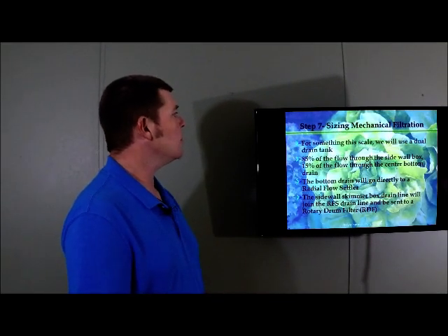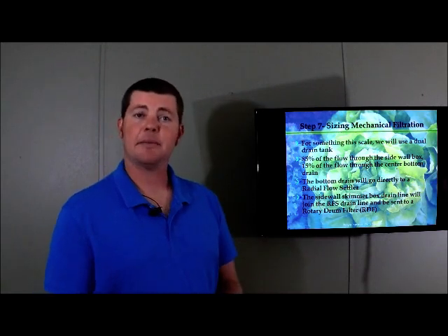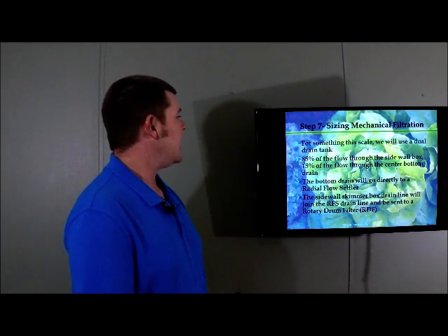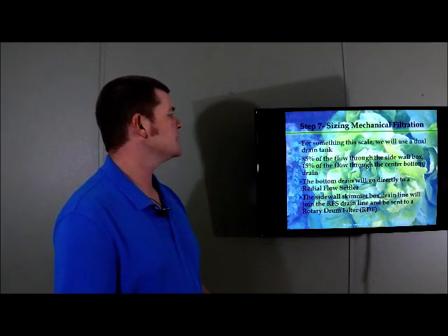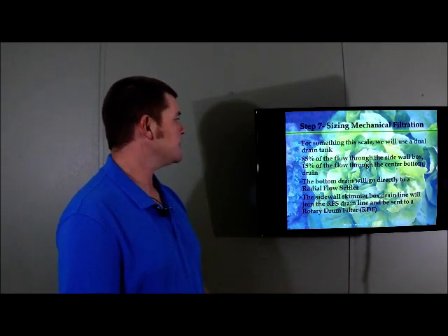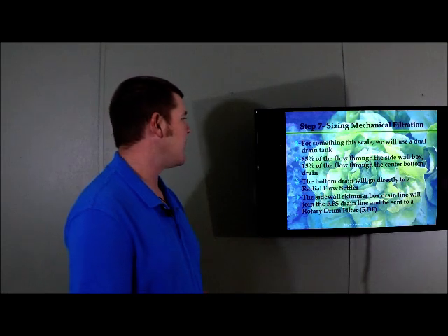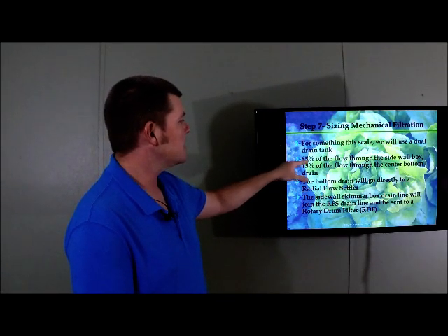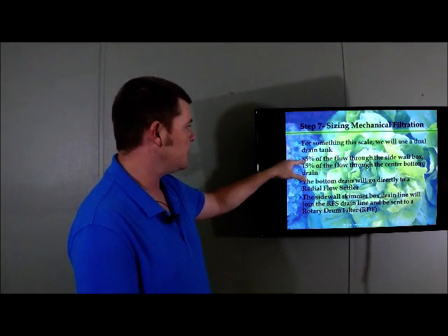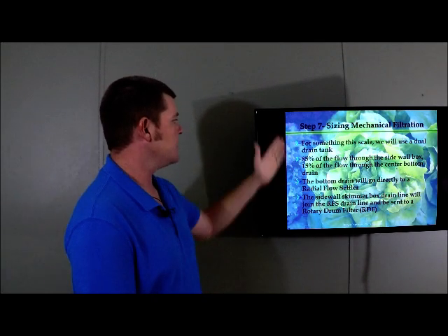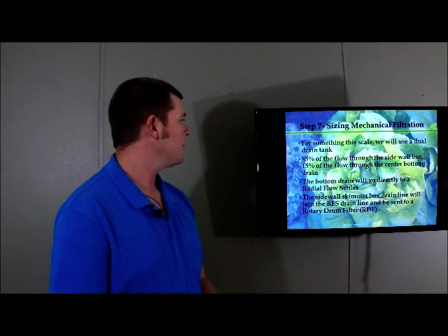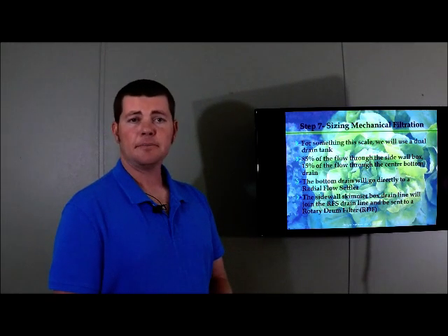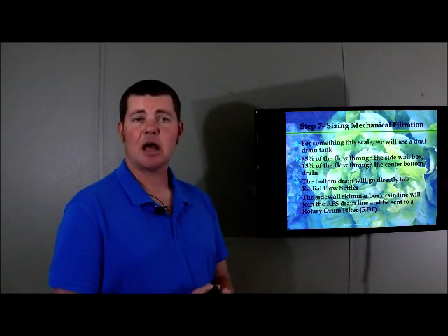For something this scale, we will use a dual drain tank, like I mentioned before. And for this design, specifically, we're going to send 85% of the flow through the sidewall box and 15% of the water flow through the center bottom drain. And remember, this can be 10 to 20%, and this can be 80 to 90%. But for this design, this is the criteria I'm laying out. The bottom drain will go directly to a radial flow settler, where it will concentrate the solids in the fish tank.